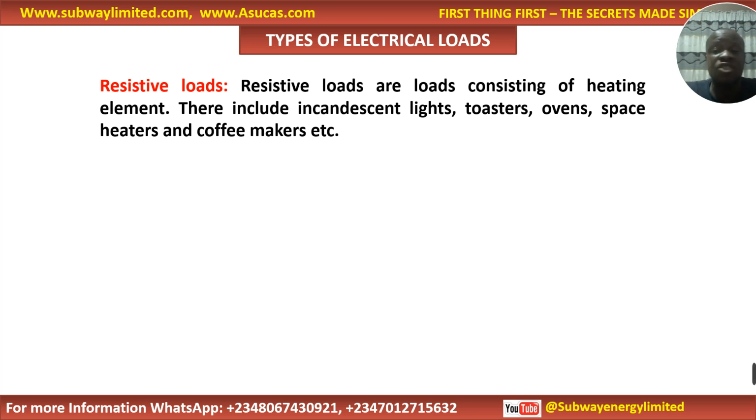Don't use your battery to run resistive loads at night. Sometimes the client is at fault. They don't know the type of load they should be running during the daytime and the type of load they should be running at night. So if the client says, I want to be running AC, collect better money and construct a better battery bank for the client, and the system will still stand the test of time.